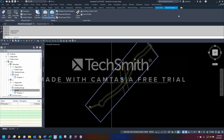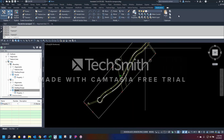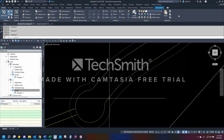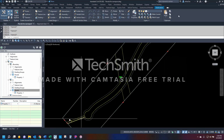Now we're really going to get into the nitty-gritty. We've got our boundary, but now we need to get the road. So I got this road in here some time ago. This was done by an alignment in another file, and then I offset it 30 feet for a 60-foot wide right-of-way. That's what this yellow represents. And at the end, I have to put a cul-de-sac, and the cul-de-sac is 105 foot in diameter. And then every curb radius, when it comes to coming into and exiting this cul-de-sac, is a 25-foot curb return radii.